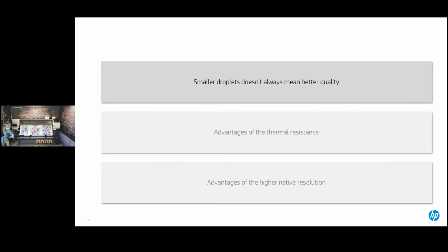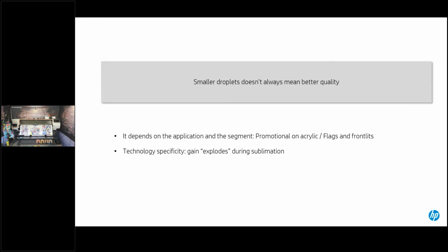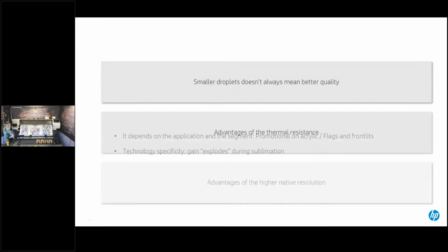Drilling down into this a little bit further, does drop size always matter, or does it always mean better quality? Well, in dye sub, it depends on the application, but as well, that dot, because it's sublimated, because it enters the fabric as a gas, the ink will explode, or it will transgress, if that's even a word, it will go into the fibers of the fabric. So a dot on paper doesn't necessarily mean a dot on fabric, because that dye is going to explode or change in the sublimation process.